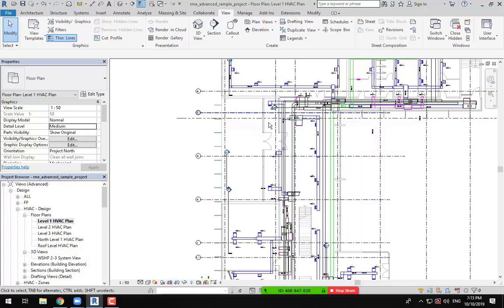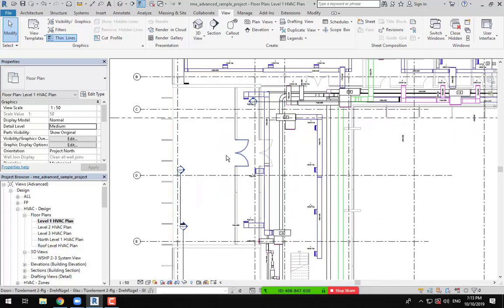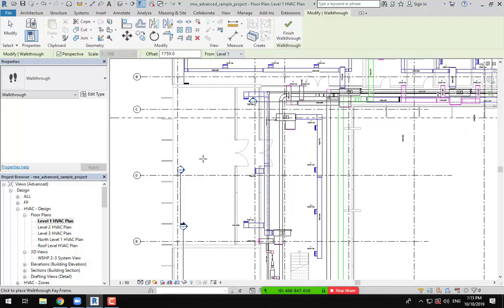How can we use this command, walkthrough? By going to the first point, the first frame, we will select the command walkthrough and put frames using this option with the mouse. Each point, each frame, will define the speed of your walkthrough or your video.